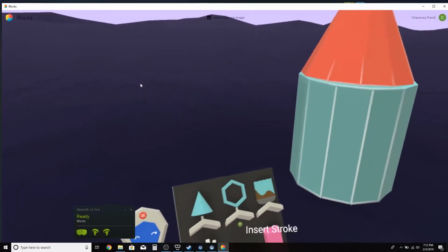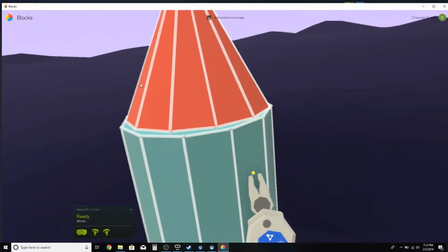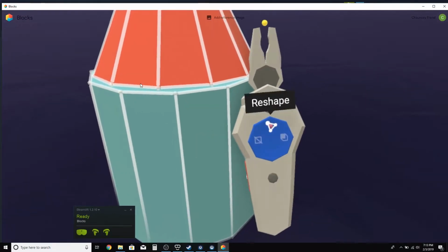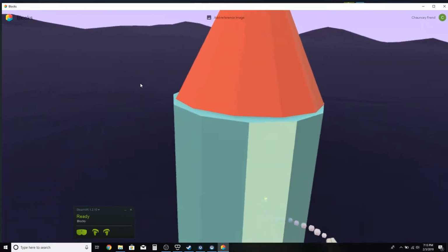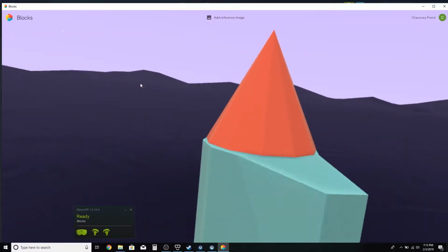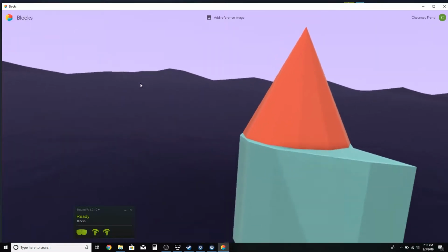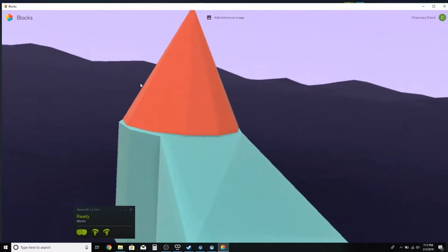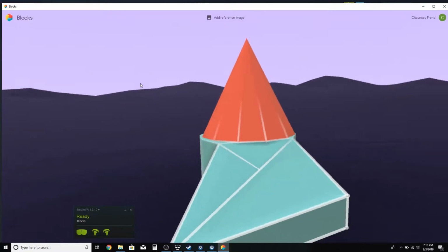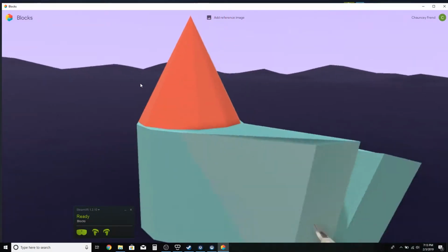The modify tool, so this is actually kind of getting closer to more 3D modeling. So if you want to do reshaping, your thumb, you go to the top and reshaping's there. And reshaping's just sort of like this. You're essentially just sort of pulling faces in different directions and twisting them. It'll give you some feedback when it doesn't like what you're doing, because certain 3D geometry won't look that good if you crease things. Like as you can see here, that's just not going to work out that well. So then it went ahead and normalized my motion there to not be so dramatic.